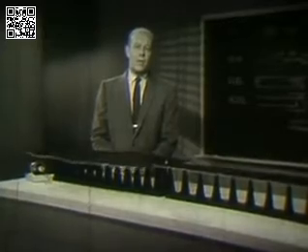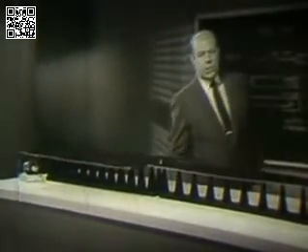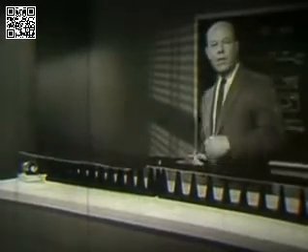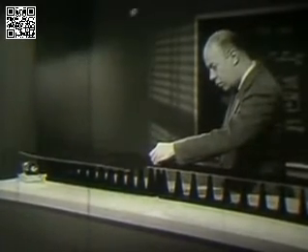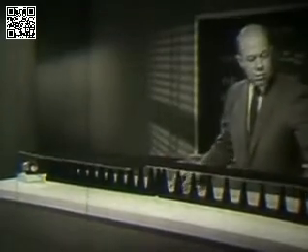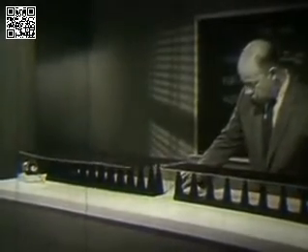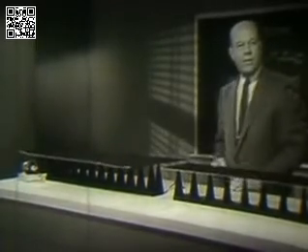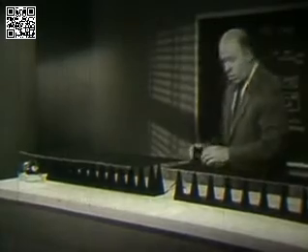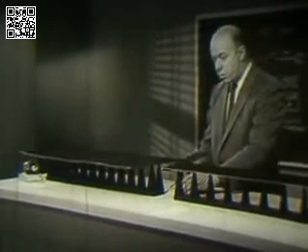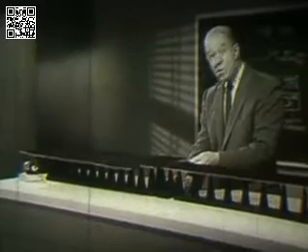Often in our technology, this partial reflection of wave energy by impedance discontinuities in the transmission path is economically wasteful, and we seek to avoid it by inserting some kind of impedance matching device between the sections of the medium bordering the discontinuity. Here is an example of such a mechanical impedance matching device. It is simply a short section of the wave medium, exactly a quarter of a wavelength long, and having a cross-arm length intermediate between the cross-arm lengths of the two machines. It is called a quarter wave matching transformer.